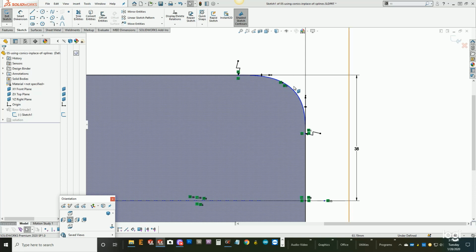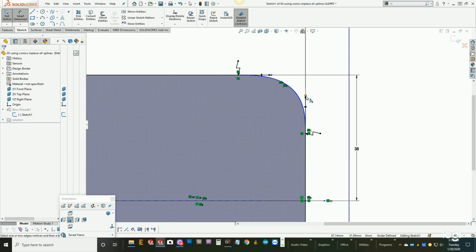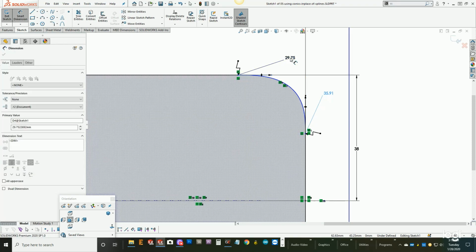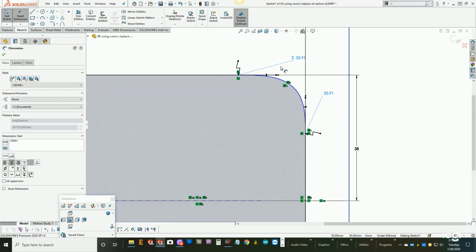And so in this example, he has a through point spline with C2 with curve continuity assigned to either end. But we know that curves like this are very hard to fully define. I mean, you could dimension both the magnitude endpoints with a value, and even create a relationship between those two if you want them to be the same. But it's a lot of work, and they're a little bit finicky. There's not a real value there.